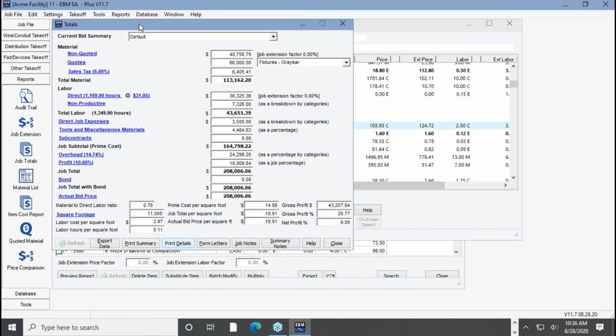The point of these pop-up webinars is really to keep it focused on a specific part of the program. So we wanted to deal with just the stuff that you deal with when you're crunching the numbers at the end. I do have one more thing I want to point out, and this is a tool that I don't think enough people know about, and it really can save you making a big mistake sometimes. It's this option called the item cost report.